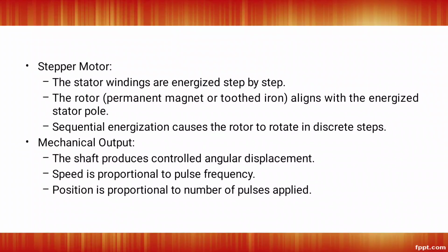Next is the stepper motor itself. The stator windings are energized step by step. Next is the mechanical output. The shaft produces controlled angular displacement. Speed is proportional to pulse frequency. Position is proportional to the number of pulses applied.